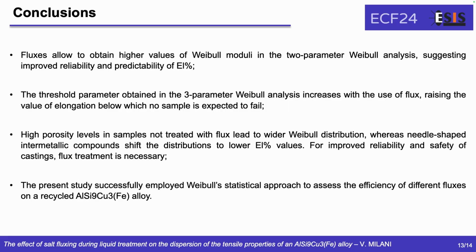So what conclusions can we draw from this work? Well, first of all, fluxes allow to obtain higher values of Weibull moduli in the two-parameter Weibull analysis, thus suggesting an improved reliability of the castings. Moreover, the threshold value obtained in the three-parameter Weibull distribution increases with the use of flux, thus, of course, raising the value of elongation below which no sample is expected to fail.